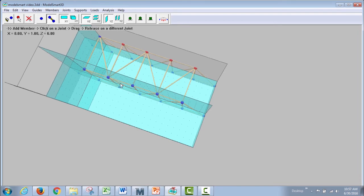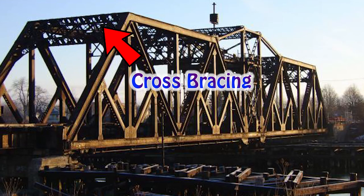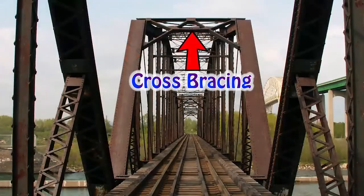Also, between the two vertical sides, you want to add some vertical cross bracing to keep your two sides vertical and plumb relative to one another. Why do we want to do this? Well, I'm going to say to you that in terms of all the bridges we test each year, about half of these bridges fail because the bridges basically lean over in terms of the two sides.